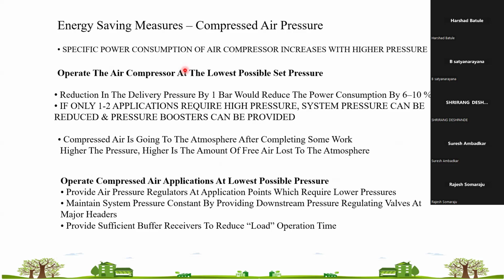So pressure drop across your compressor acts as a barrier. If you are allowing more pressure drop in the system, your energy consumption will be on a higher side. As a thumb rule, for every 250 mmWc of additional pressure drop you allow, air energy consumption will increase by 2%.